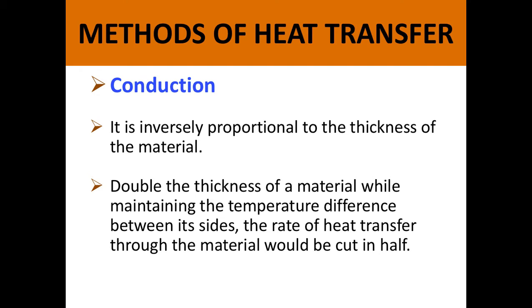The temperature difference is important because the larger the temperature difference, the larger the heat transfer. So if you have a 70-degree inside environment and a 0-degree outdoor environment and a material half-inch thick, if you change that to an inch-thick material, keeping the temperatures the same, you cut the heat transfer in half.